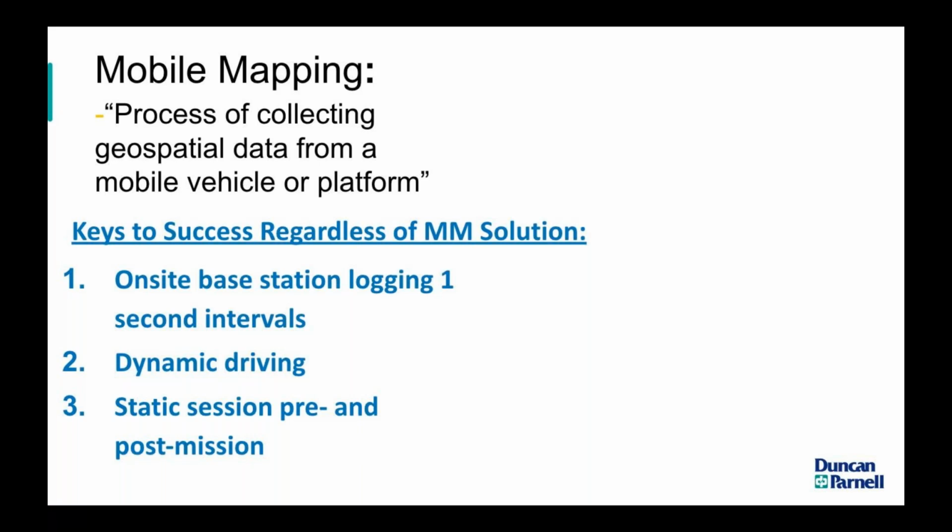So that's really the arena we're drilling down on with these products today, the MX7, the MX50, and the MX9. Now, regardless of which solution you use, Trimble or otherwise, those three best practices will help ensure the maximum success, at least of your field data capture. So for that number one, on-site base station.